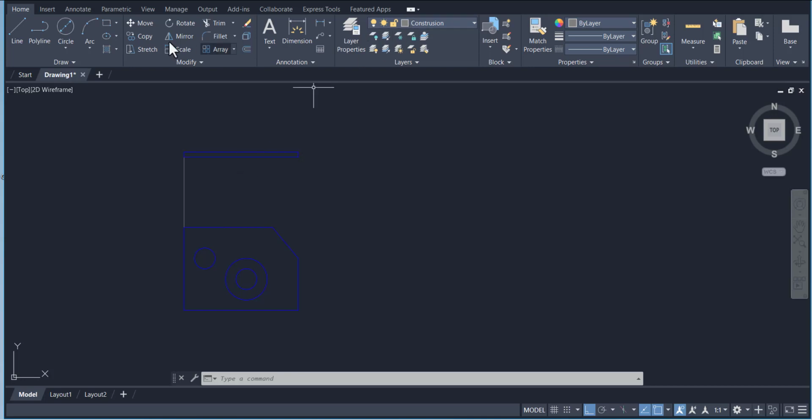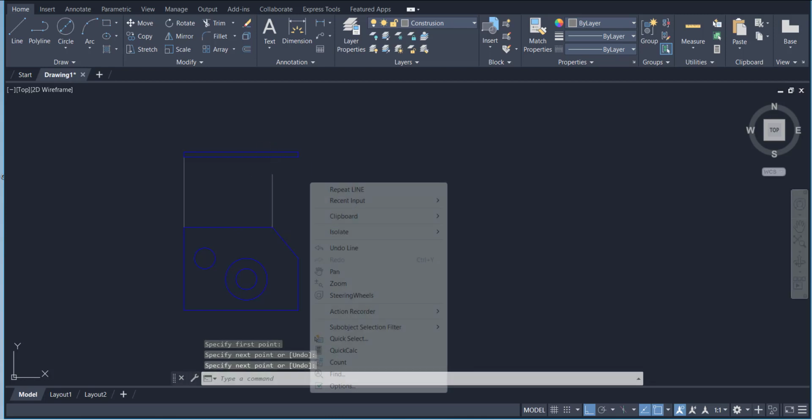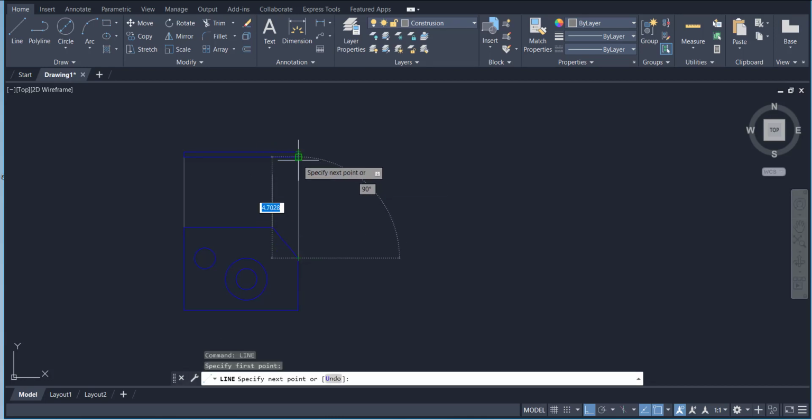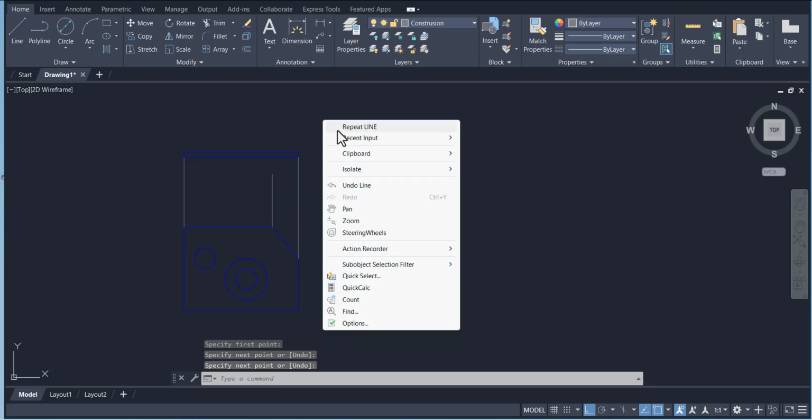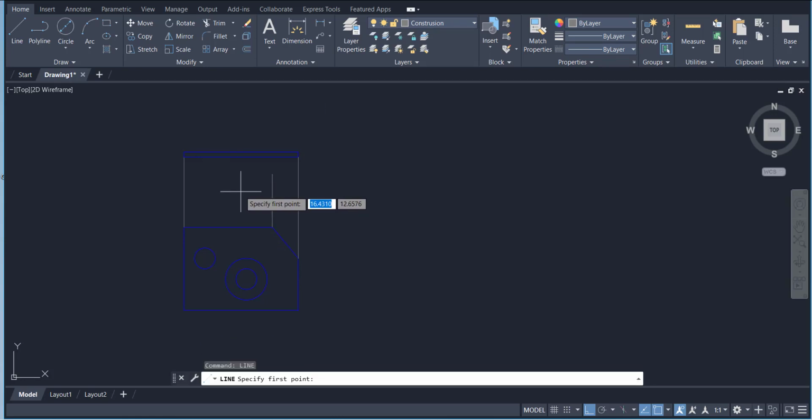Okay, now go to construction, and now you know that to transfer the view from this front to top, we have to draw some construction lines for every point on this view. That's how we transfer the view to the other view. So like that, for this one we have to draw a line, and this one move to here, and line tool, and now we have to draw for this circle. So every point, this point we draw a line, this point, and it's tracking, and we are transferring the view to this.